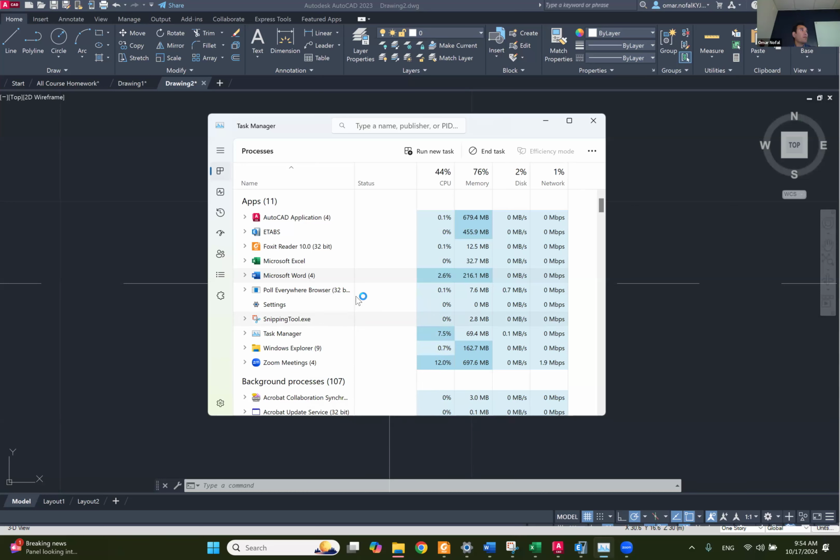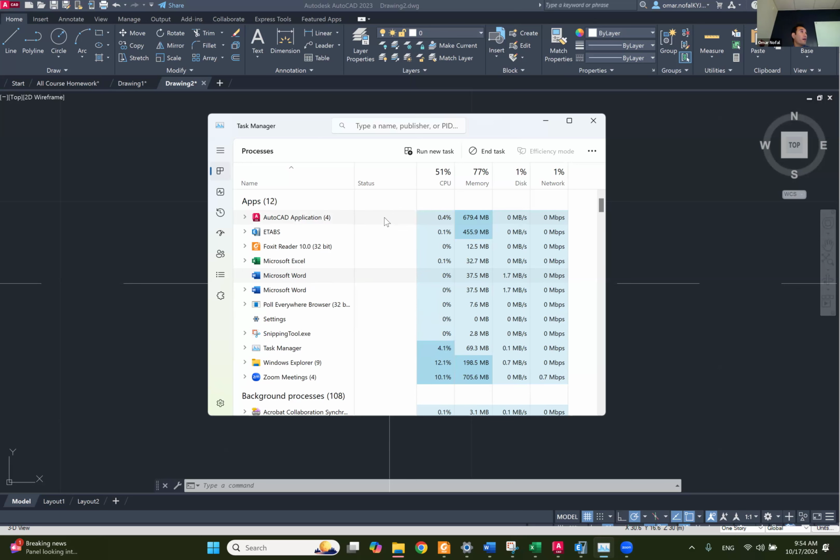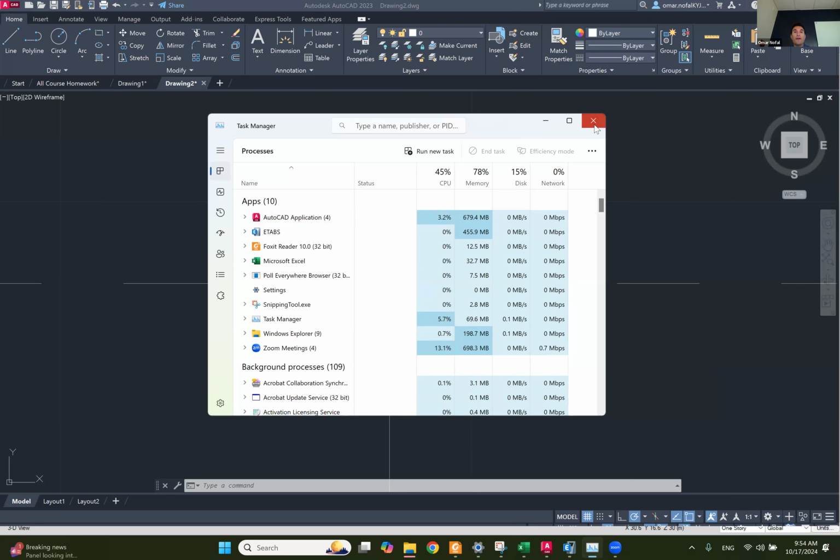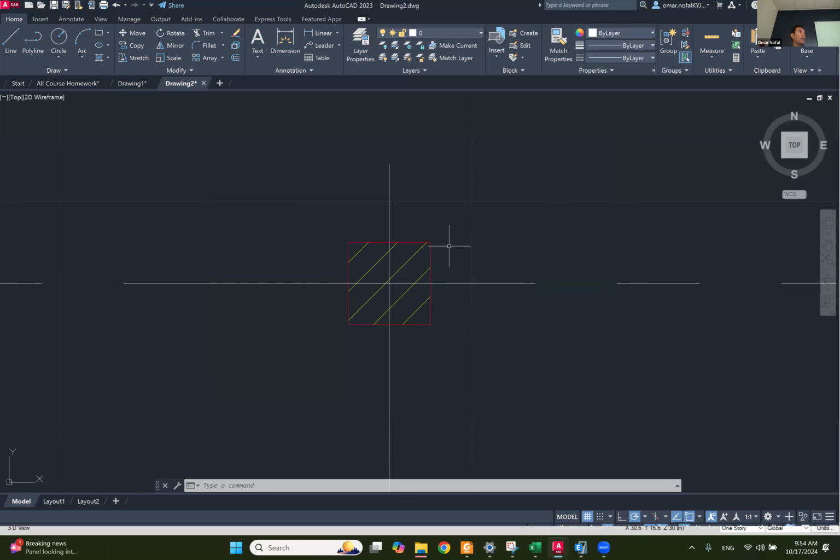Everything has to be a polyline. When it comes to closed objects like walls, columns, and slabs, all of these need to be polylines. Polyline means, let's say I draw a line like this, and one like this, and one like this. You'll feel that's a closed object, but it's not, it's like broken lines. But if you use polyline, or PL,